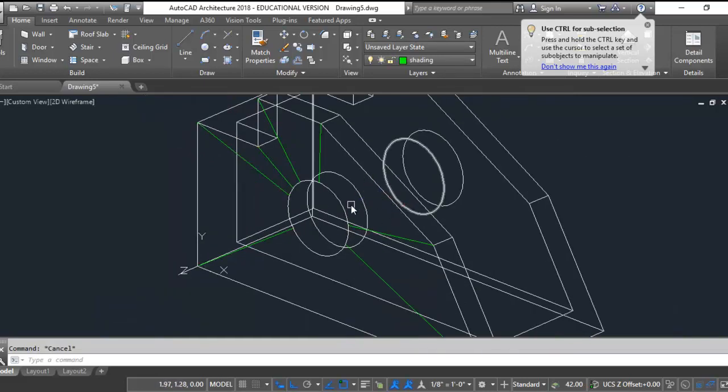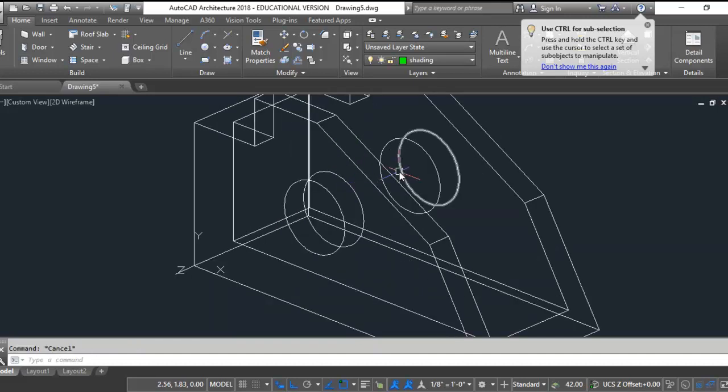If you paid attention to what I did, I basically trimmed away and then added a circle and trimmed again to get a piece of the circle corresponding with each segment. Now if I delete all of my original shading lines and I use the command rule surf, I can pick my first curve and my second curve and it'll shade that piece of the pie.